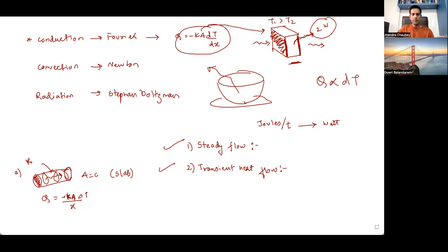No, I don't think we do. Mostly the material is called isotropic. Isotropic is basically a material which has a uniform or homogeneous K. Let us assume you have homogeneous K, because I saw the numericals, they don't have any such equations. What they have given is directly K. So when K is simply a constant value, the heat transfer from one end to another end, if the temperature difference doesn't change, will be constant.